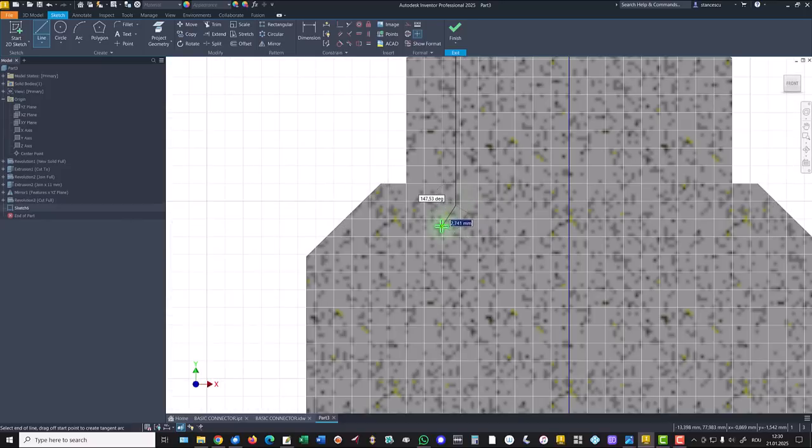Now be careful, I draw a sloped line, a vertical line, and again a sloped line. Not parallel with the other, even if they are parallel. I go to the left, I press the left button, and I draw a fillet here.